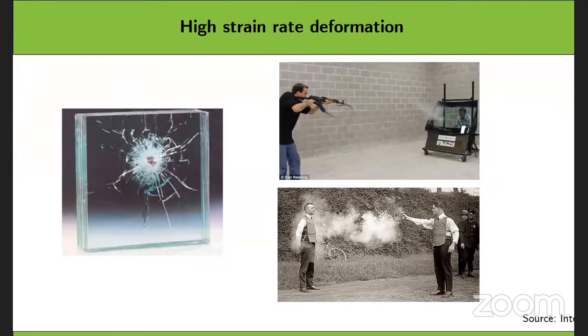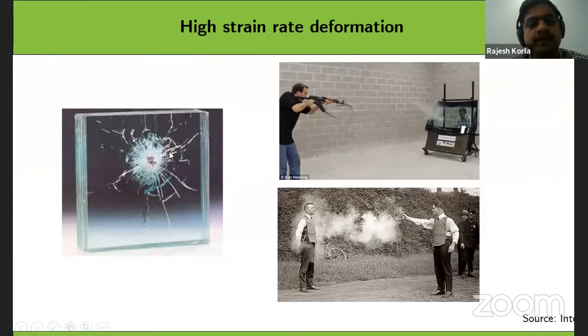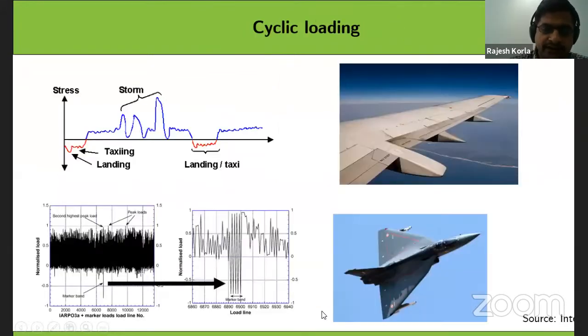And also here the fracture property is very important, basically because fracture is happening by so many branchings, so that it can absorb all the energy, rather than simply 2-3 surfaces being created, which would absorb very little energy. So more impact will transfer to the person behind the shield. So here we require very high strain rate resistance.